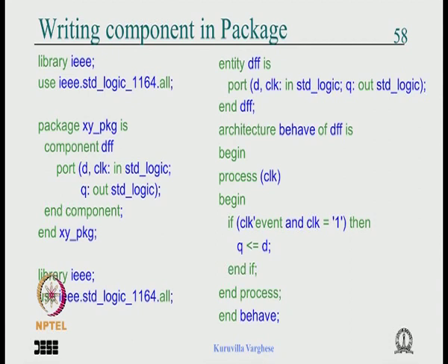Sometimes you work with a simulator like ModelSim, sometimes you work with a vendor tool like Xilinx ISE or Xilinx Vivado or Altera Quartus tool and so on. Okay. So how to compile a particular package into a library is tool or vendor specific.